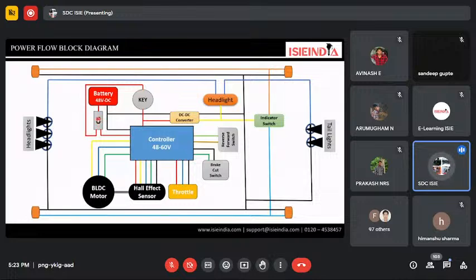Basically, an MCB provides protection from overload and short circuit in any circuit, and it can save the auxiliary components along with components like the controller and motor. After the circuit breaker, we give the positive power supply to the controller. As I mentioned, in the controller we have 5 basic wires: 2 are the input and 3 are the output.